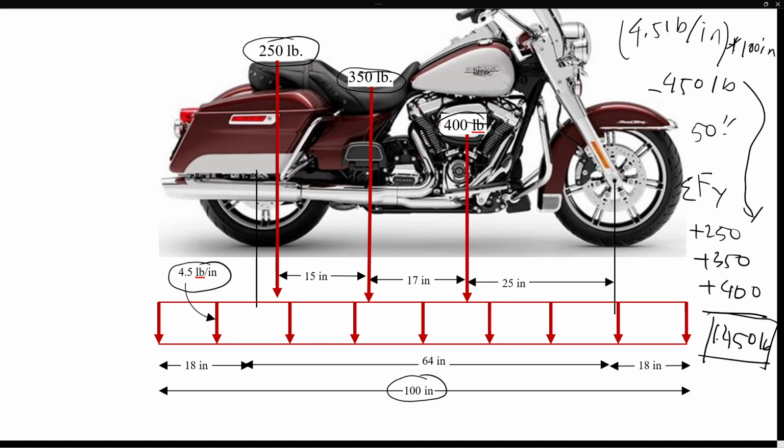However, for the location of this force, you have to apply the thing called the moment principle or Varignon theorem, which is simply that the moment produced by this resultant force with respect to any point will be the exact same as the moment produced by the individual components of the forces. So in this case, that 1450 pounds total resultant, we calculated that moment.